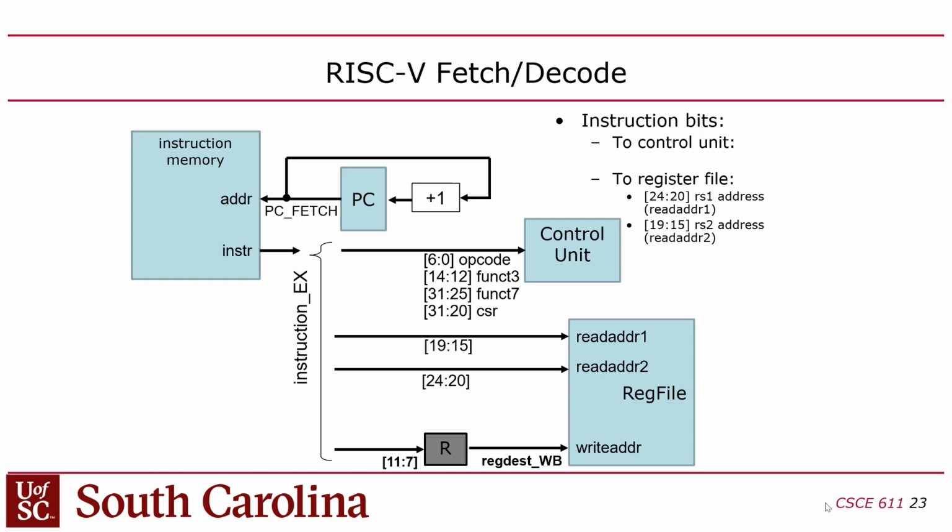You don't want to write back in this cycle. You want to write back in a future cycle, one cycle into the future. So you put that register in there that will delay the write by one cycle. So I'm going to read in the execute stage, but I'm going to write in the write back stage, which is in the future, one cycle later.